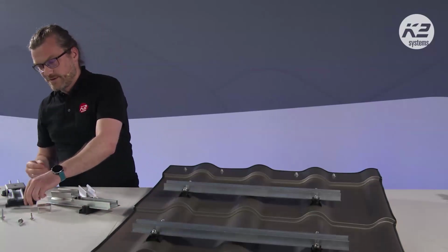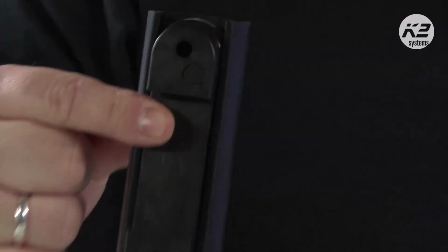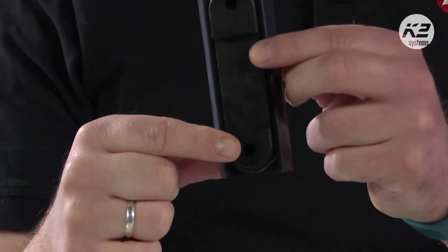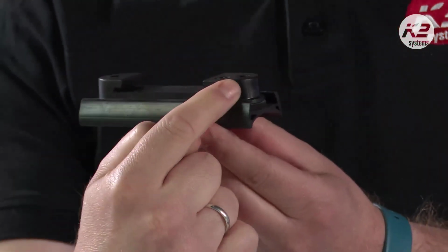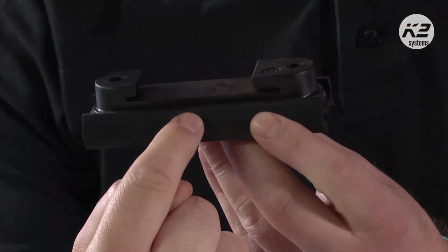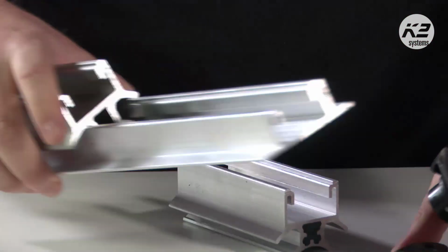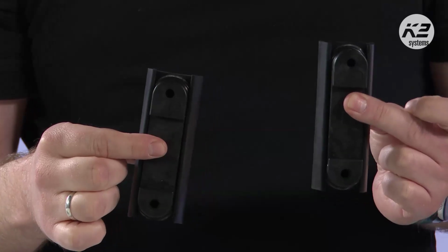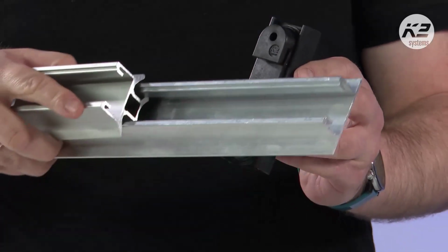What's important to say about basic clips is our K2 logo here on the top. You will see it's only on one side. Why is it here? Because there are two ways to install the basic clip: in this direction and in this direction. You will see here also a different space inside the basic clip. Why is it done? It's done for easy installation of the basic rail. So you install at the beginning the basic clips with the logo on top. Then you can just put your rail inside.